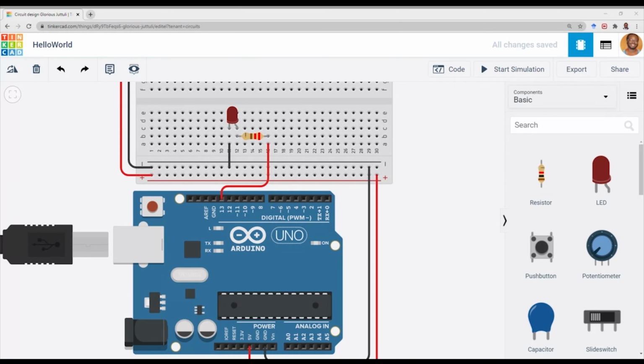We want to see the Arduino programming scope and also how to write Arduino code for a Hello World program. In Arduino, there are two main functions: a setup and a loop. Upon reset or powering on, when the Arduino wakes up, it starts by looking into the setup to configure itself. So upon start, it goes straight into the setup function.